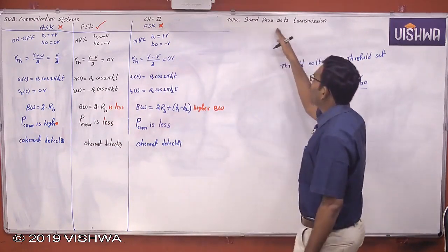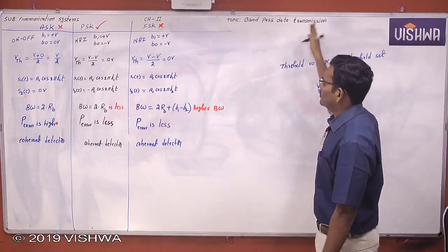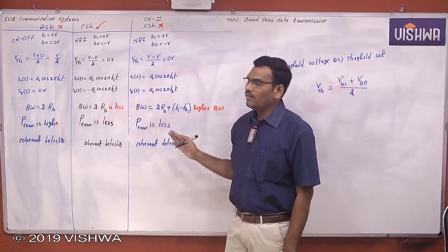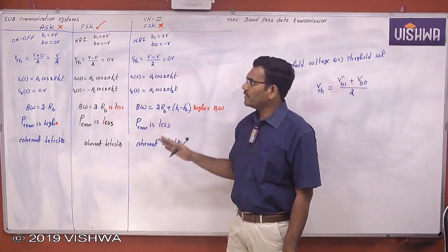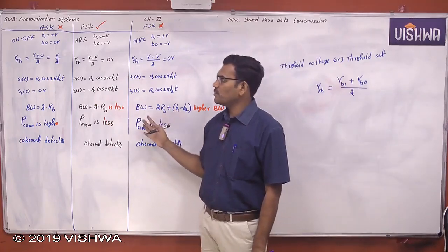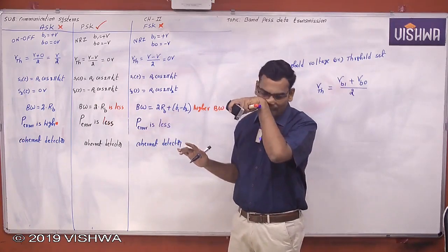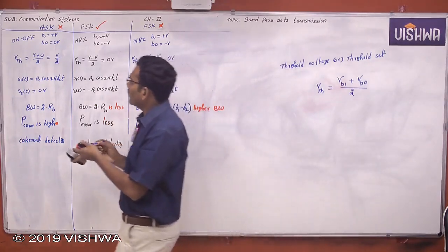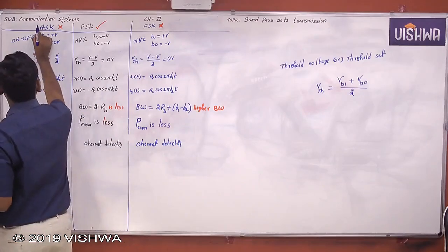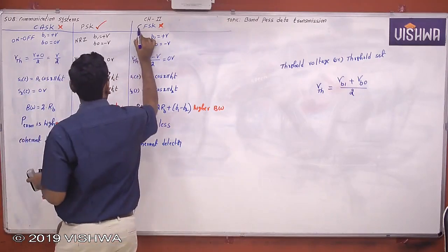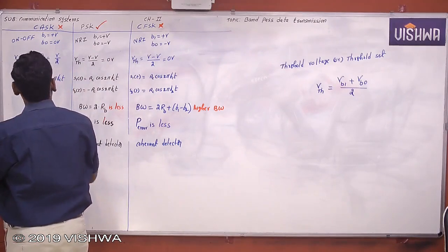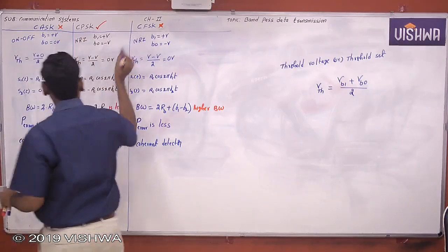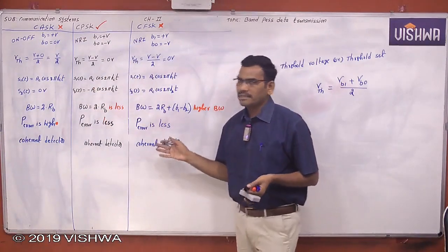All these three band pass data transmission techniques suffer with demodulation, which is nothing but coherent demodulation, where the quadrature null effect or frequency effect takes place. Now phase mismatch and frequency mismatches are taking place. Okay, these are the disadvantages of this modulation technique. That is the reason why this is called coherent ASK, coherent FSK, and coherent PSK. Don't confuse, that is nothing but normal ASK, FSK, PSK only.